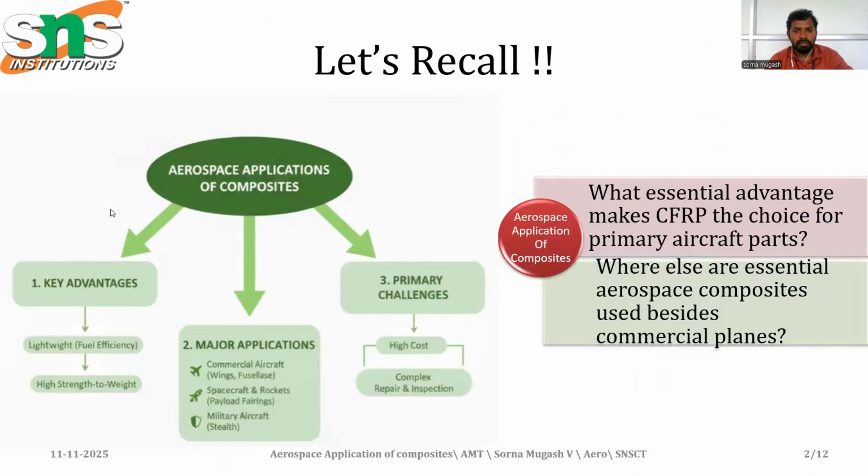So, first of all, let's recall the aerospace applications of composites and the key advantages: it is lightweight with fuel efficiency and high strength-to-weight ratio. The major applications are commercial aircraft wings and fuselage, military aircraft, and rockets. The primary challenges are high cost and complex repair and inspections.